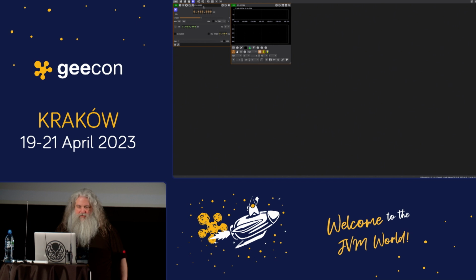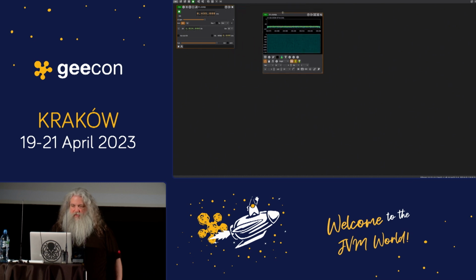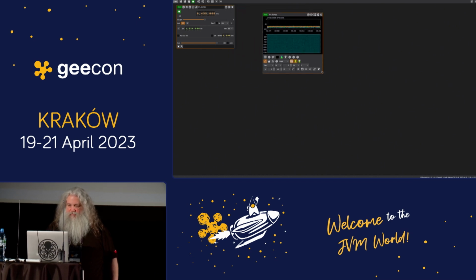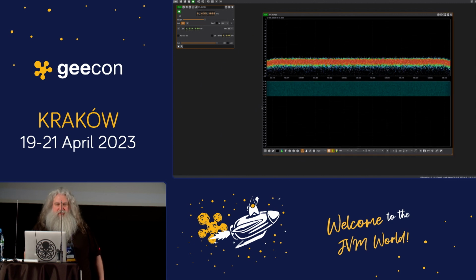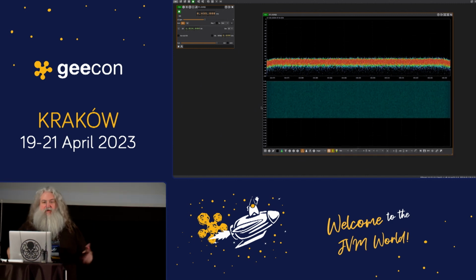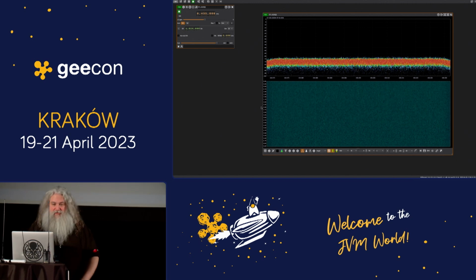And so here we can see, there it is. Now I've got to turn that on. I've got to turn the gain up. And if I hit start, you can see, if I make this bigger, this is super tiny on my screen. This is a picture of this particular bit of spectrum. And right now it's tuned to 433 megahertz because that's where it decided to start.